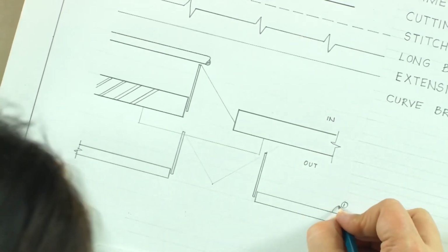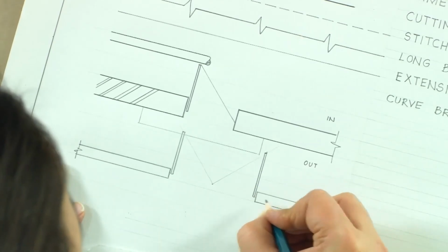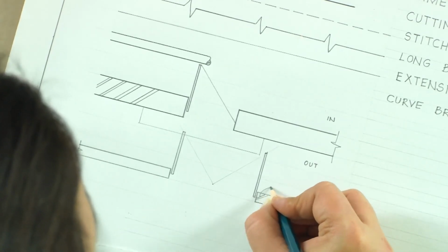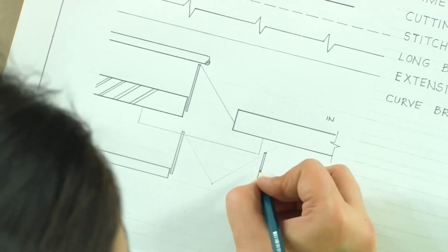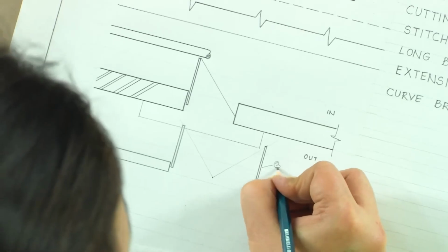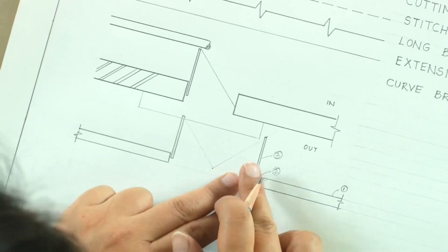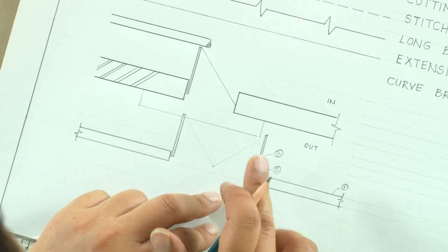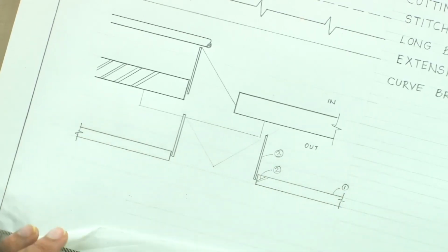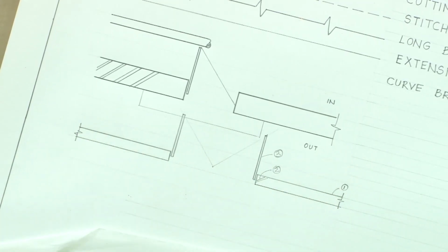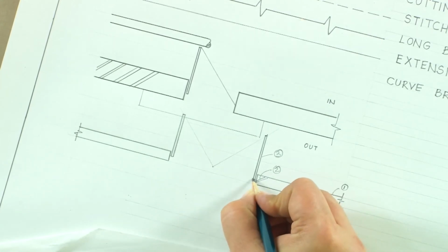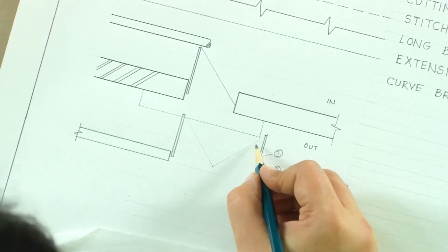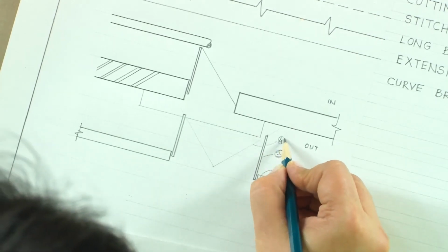So that's the thickest. The second is the hatch that we are going to use. That's going to be the second level of darkness. This is the third level of darkness, which is wood. Since it is very thin, you would usually not use a hatch in this, but it may be used if it is a big scale where you can see a substantial thickness of this wood. And then the fourth level of thickness is this path.